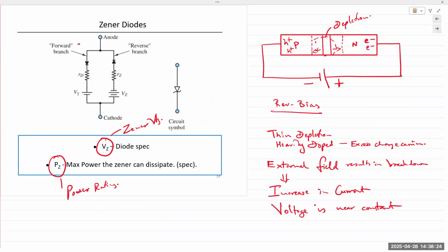Okay, so in the forward bias, Zener diodes behave like a regular normal diode made out of silicon. It'll take 0.6 to 0.7 volts for it to conduct in forward bias, exactly the same diode characteristic. In reverse bias, if you take any normal diode and apply a reverse voltage, you would not see any current. If you keep on increasing the voltage, the electric field density keeps on increasing, and at some point, minority carriers are ripped out of their lattice structure. A large number come free, and then avalanche and impact ionization effects occur, and you have a large current flowing in the reverse bias. This is known as the breakdown, right?